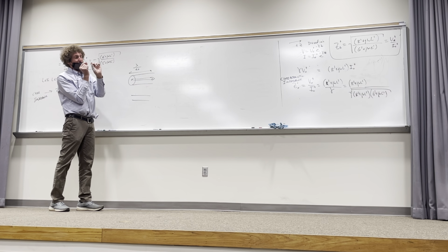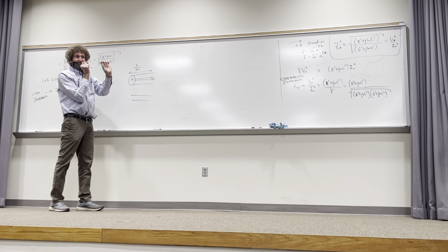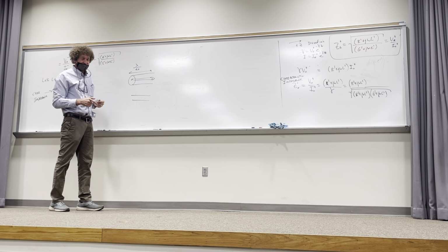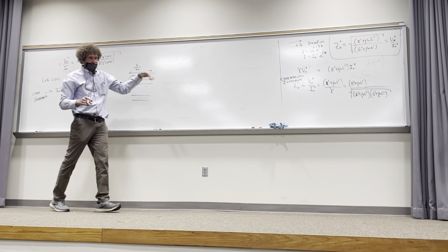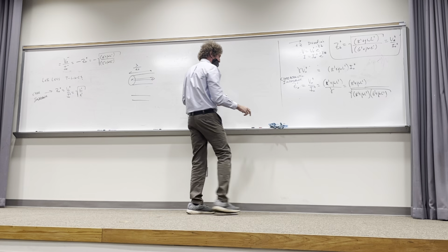They have a 75 ohm cable and they connect it to something and they do their engineering, and you're going to see how we do T-line engineering, and it says it should be matched. They don't realize that the length of this thing is only maybe 1/30th of a wavelength. Effectively, they just soldered on two pieces of wire. There's no characteristic impedance to that. So just be aware of this. This is a common mistake. That comes later, but I just wanted to tell you now.